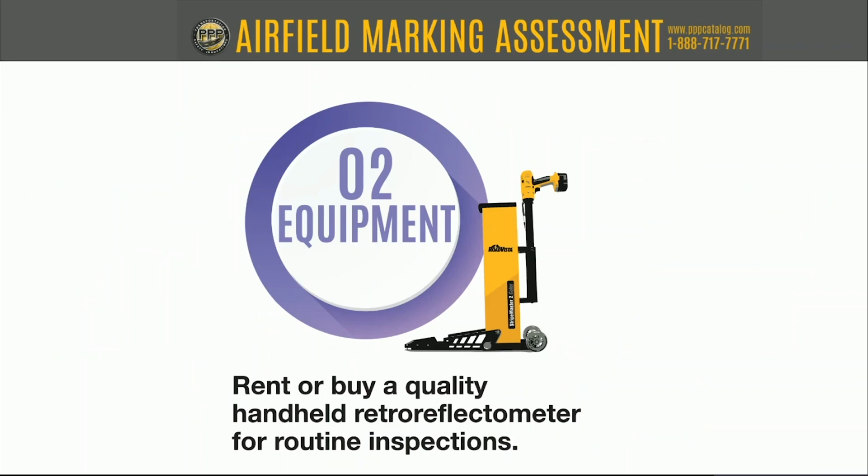Yeah, I think the Stripe Master 2Touch is a really good unit. It's very reliable. One thing that we haven't really mentioned is that what I like to do with this for my clients when I'm doing quality assurance is to measure all of the markings per the ASTM and per the FAA spec. But then because it's GPS enabled, I like to upload them to a KMZ file for Google Earth, and I plot it on their airfield, and they think that's so cool. And I can show them where it passes the FAA criteria, where it fails.